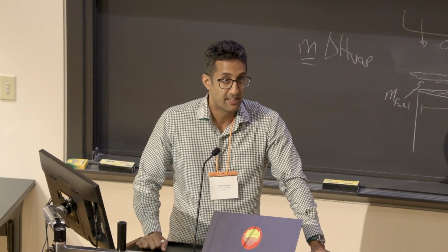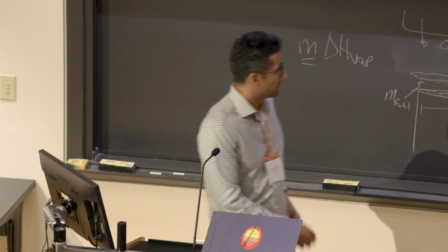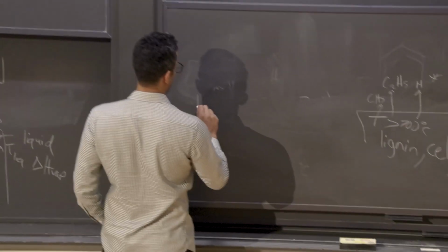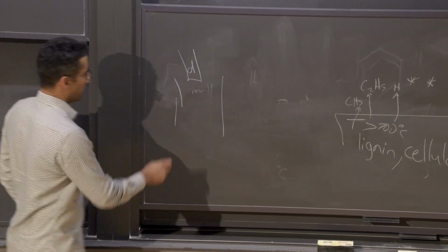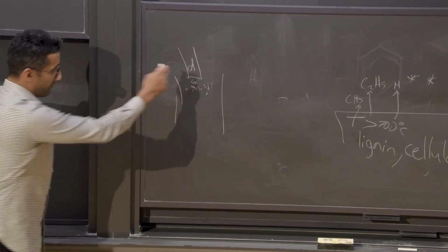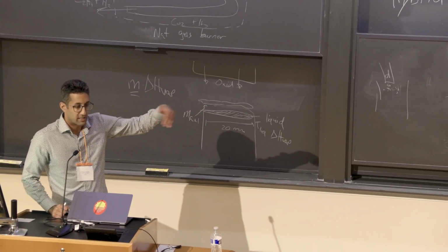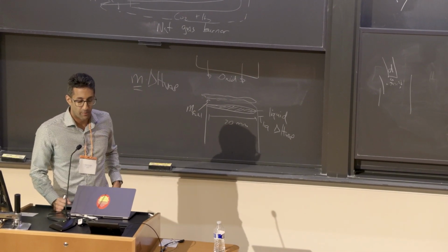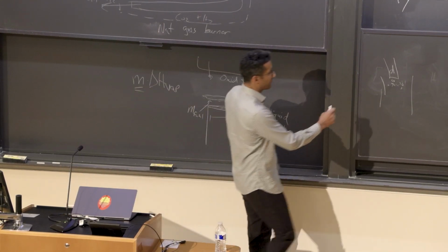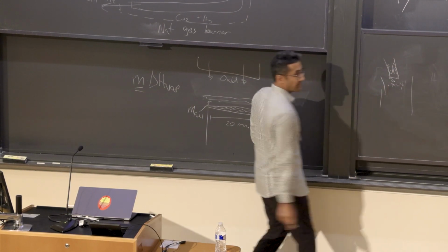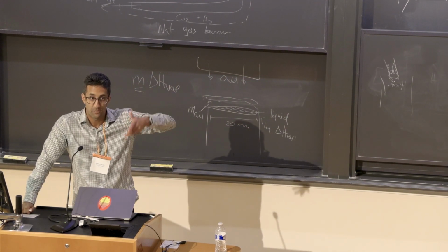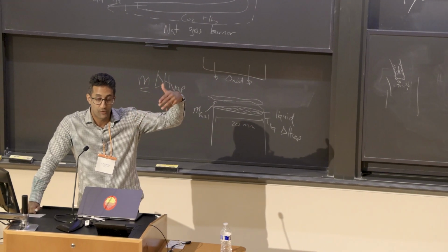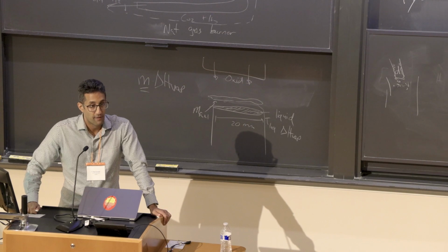It also happens in diesel injectors. If you have a diesel fuel inside of an injector going into a chamber, this injector gets hot over time, and eventually you form things like gum, like solid depositions inside the injector. And that's all not a combustion process. It's a liquid phase pyrolysis process of things happening inside the injector, and these gums form. And again, people try to build models for that.